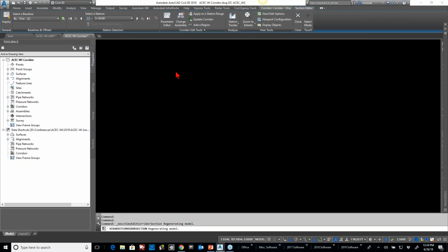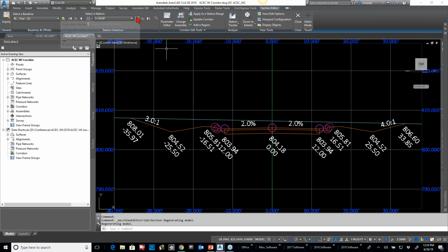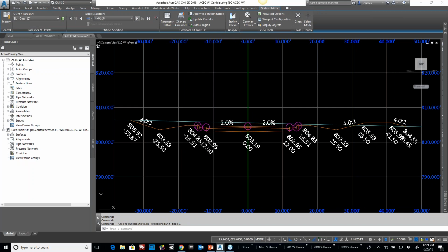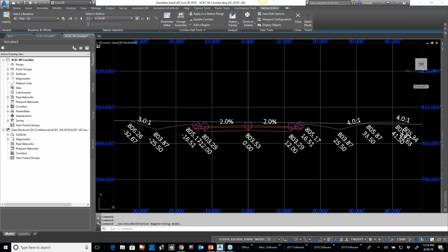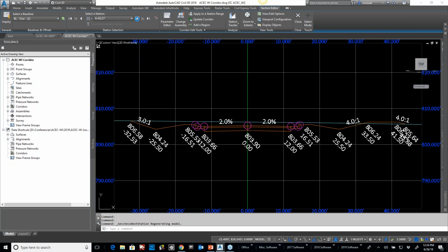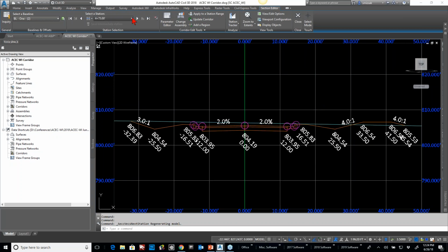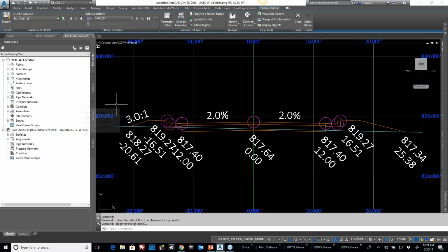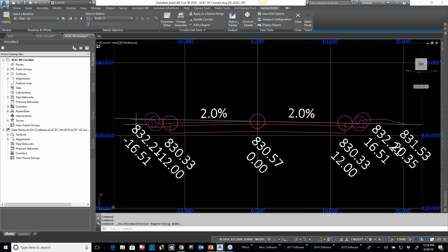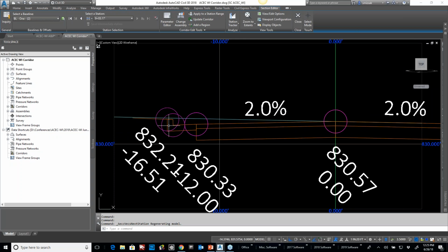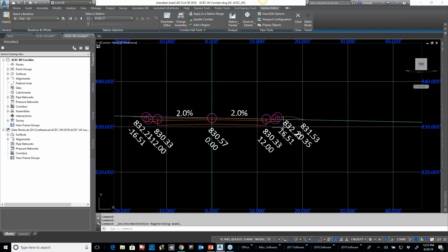Section editor. And we will see that at 350, I'm in a ditch. Still in a ditch situation. Now I'm at 450, so now my value equals 1. So now it will actually read the value all the way through, and it would determine, hey, should you be cut or ditch or fill? And then anything over 700, 700 still equals 1, so it's going to be automatic. So it says, yep, fill. And now the rest of this is saying, yep, always do a fill. And this is what we're seeing on the left-hand side, is that the fill doesn't work, or because it's not finding the proper situation.